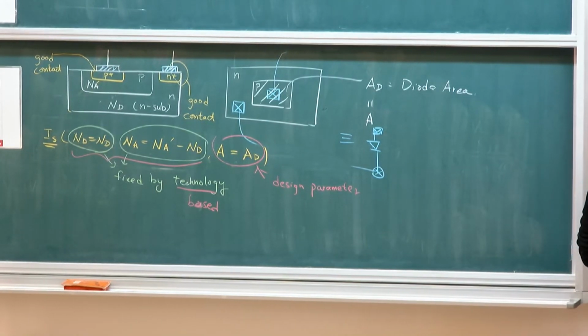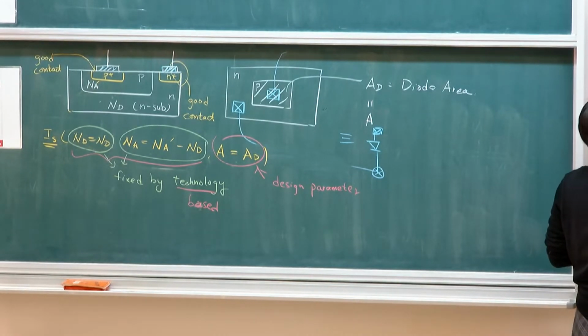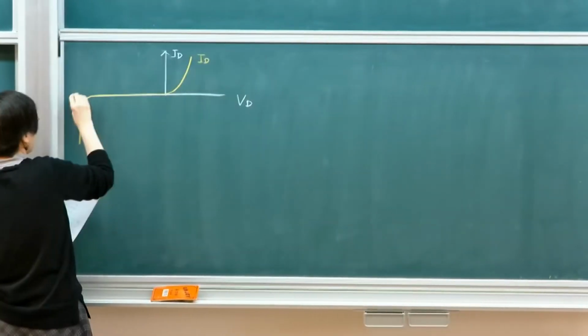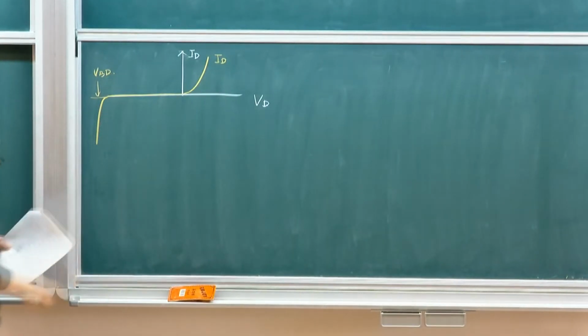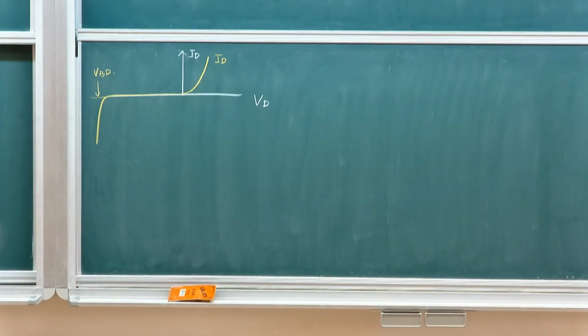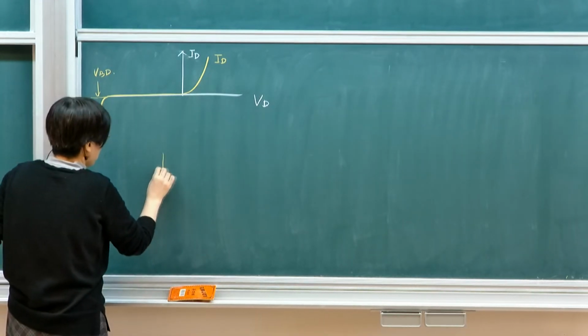This is forward bias, exponential increase, and then it might break down. So this is the breakdown. If I give you a diode, you can just go buy a discrete device and do the sweep. You just sweep the dial. So this is a very simple setup.